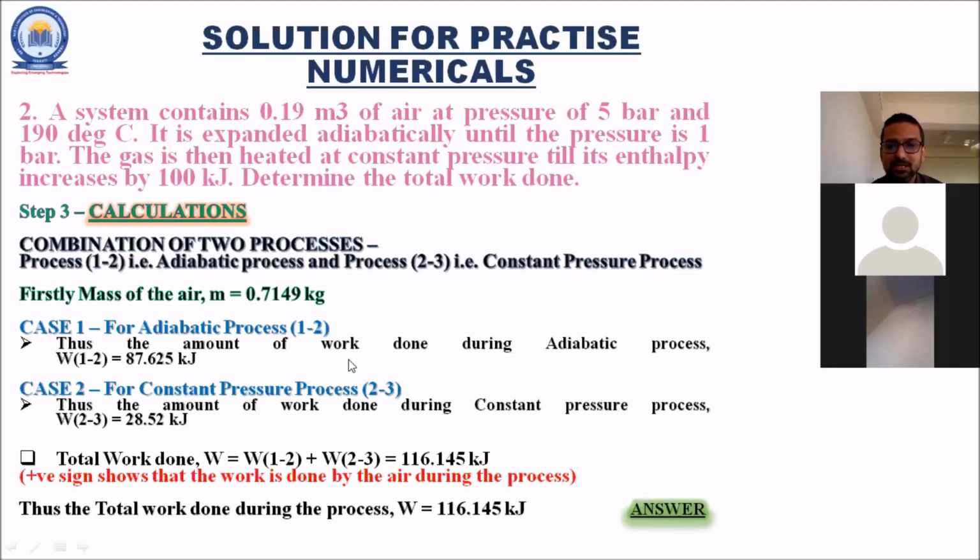Okay, roll number 2 is asking how the mass is calculated. Dear student, it is very easy to calculate. For mass, it is P1 V1 is equal to mRT1. We have the value of P1, we have the value of V1, we have the value of T1. Capital R we are assuming, that is 287 joule per kg Kelvin. So substituting these values, you will get the answer for mass. Roll number 2, have you understood?